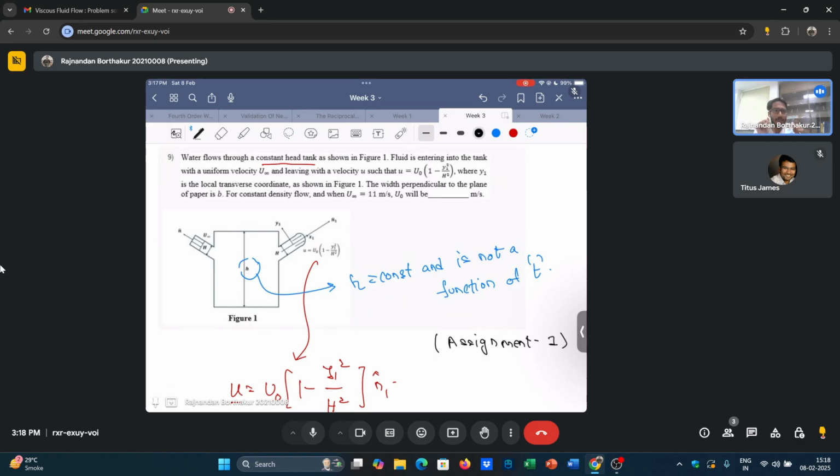At least a bell should ring in your mind when you see such a problem. Even if it doesn't appear trivial, you can appreciate that fluid is coming in and fluid is going out, so something has to be conserved. What has to be conserved is the mass of the fluid inside the control volume. So the first thing, you must look for mass conservation, and the most appropriate way in fluid dynamics to apply it is the Reynolds transport theorem.